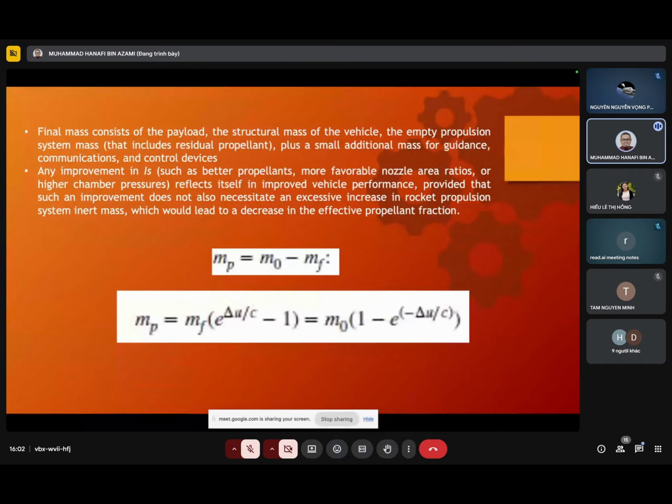The divergent part, after the throat, diverges so the area is as large as possible, and then it closes, converges a little bit. So it's a bell, to avoid this separation.